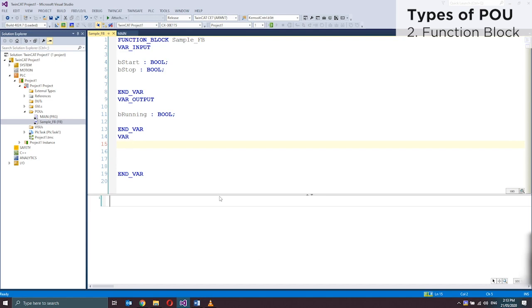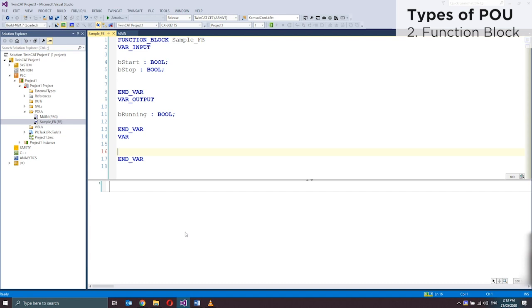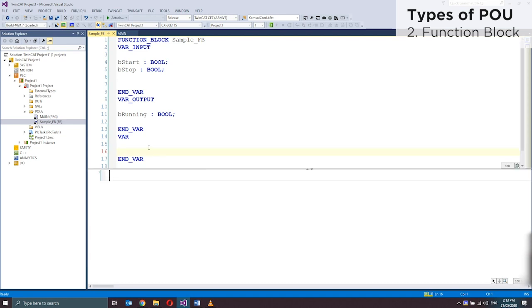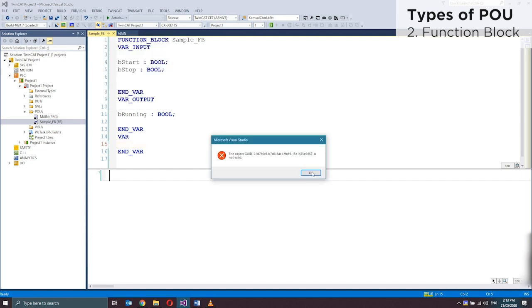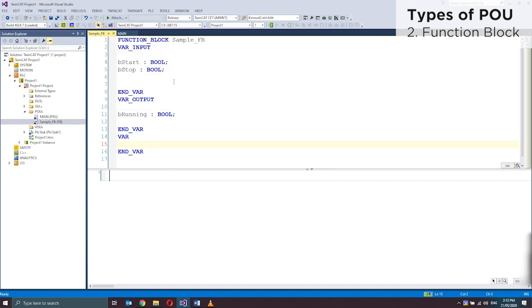Each instance possesses its own identifier, the instance name, and a data structure, which contains its inputs, outputs, and internal variables. Instances are declared locally or globally as variables, whereas the name of the function block is indicated as the type of an identifier. So you could create an identifier for every instance of the function block you will create.